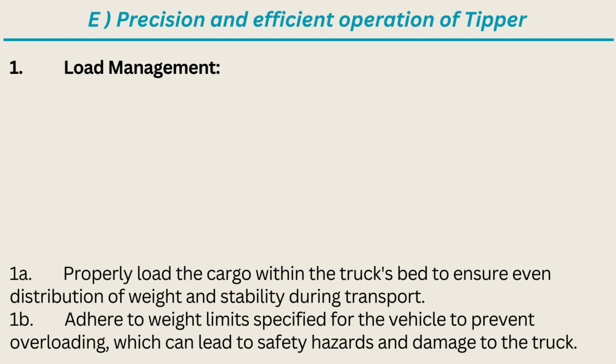1. Load management. 1A. Properly load the cargo within the truck's bed to ensure even distribution of weight and stability during transport. 1B. Adhere to weight limits specified for the vehicle to prevent overloading, which can lead to safety hazards and damage to the truck.